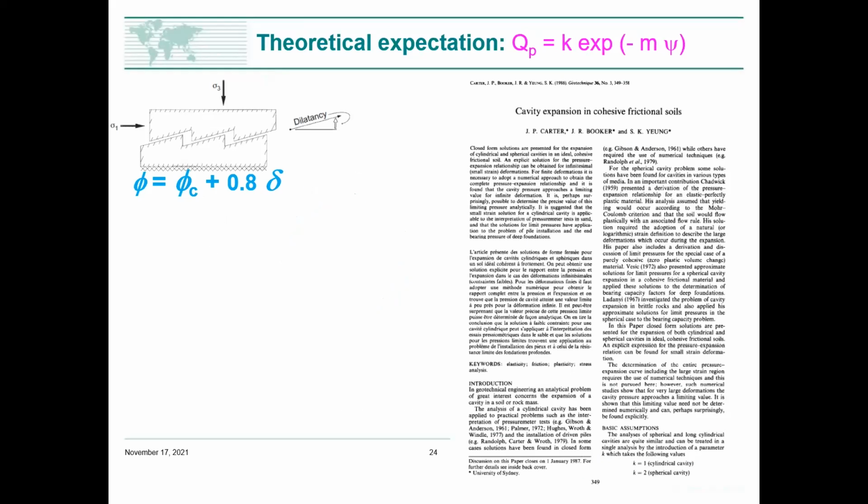Now, let's go a bit further. The simplest possible reasonable model for soil strength is this one here, which is that phi dash is critical phi cc, plus dilation. Now, this is derived by Peter Rowe, theoretically from micromechanics. Malcolm Bolton, bless his heart, said Rowe's equations are way too complicated for practical purposes. We can just put a coefficient in here of 0.8, and that is as good as Rowe's very fancy theory. The nice thing about cavity expansion theory, I've alluded to its symmetry.